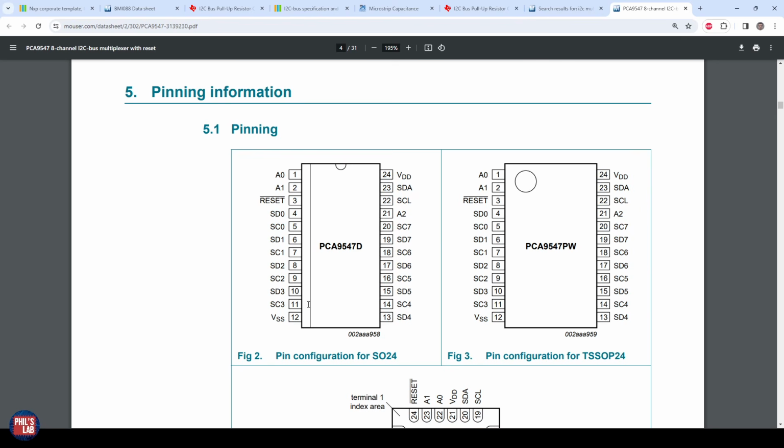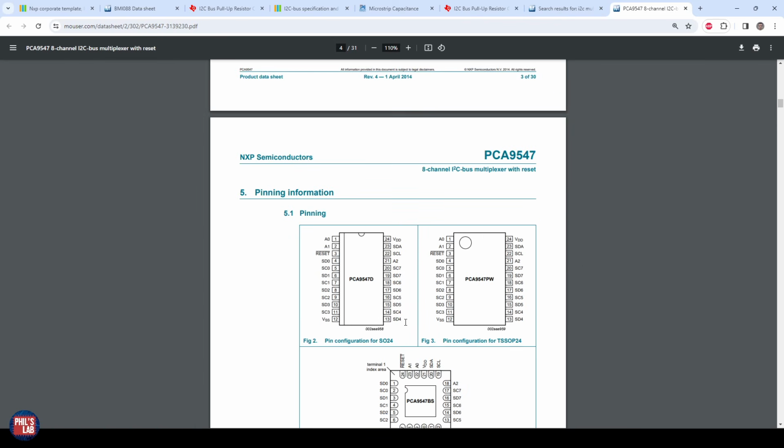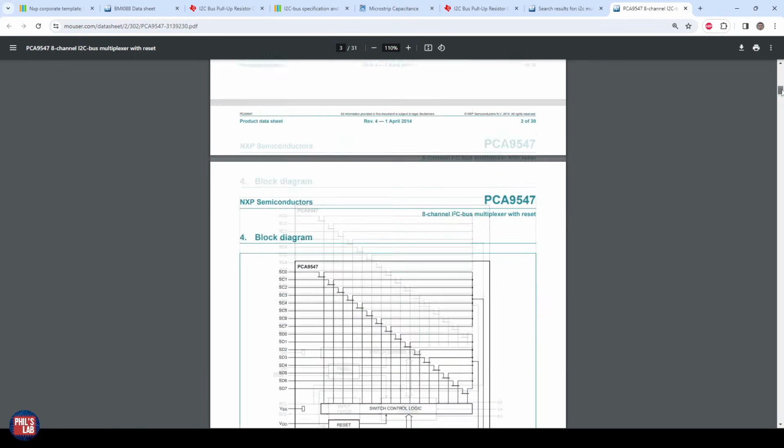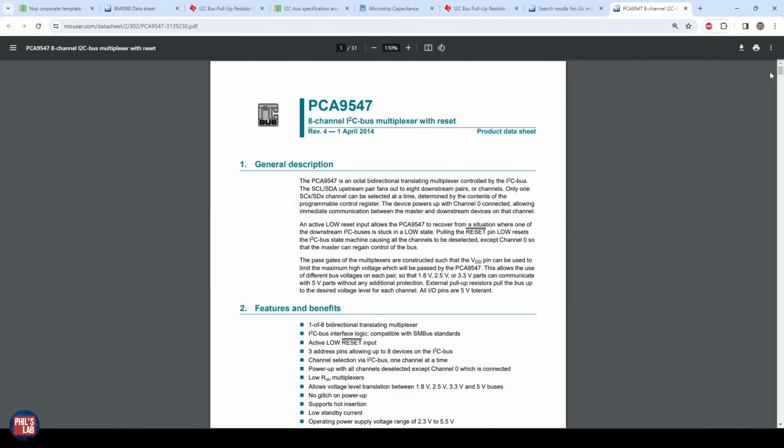So on a single I2C bus seen by, for example, the host controller, we can attach 8 of the same peripherals. There are these options as well, and typically these multiplexers might contain buffers as well and might help with level shifting and so forth.